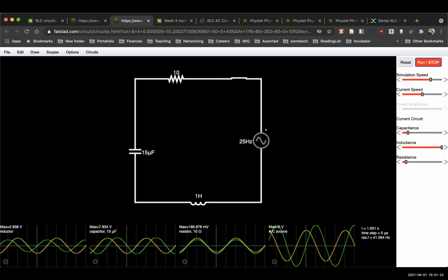That's the frequency at which we should apply our driving force, our push, to achieve maximum swing response. So we can get the largest load delivered for the smallest input power if we have a source with the right frequency.